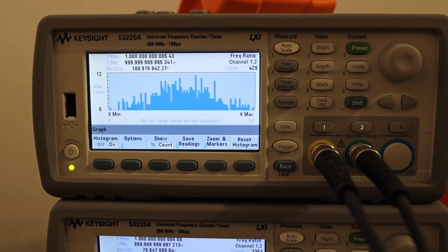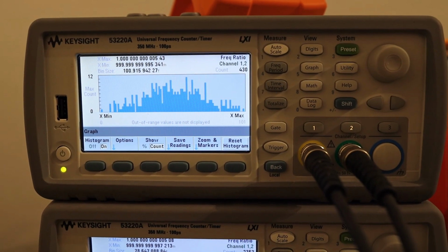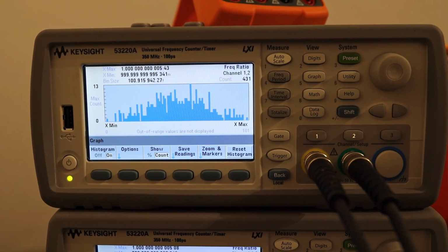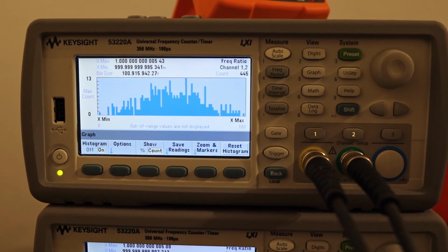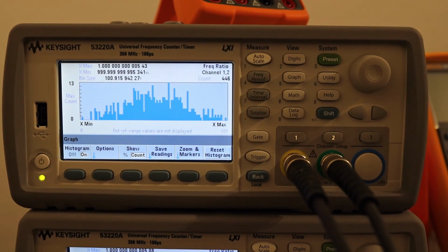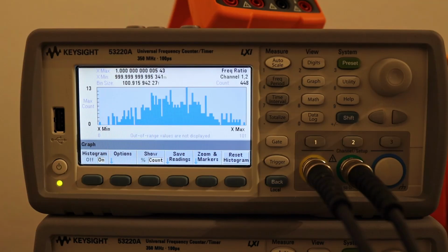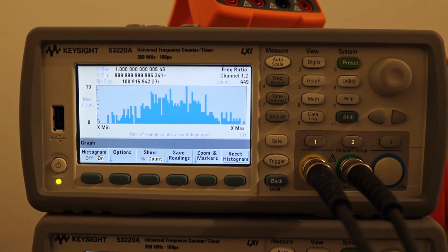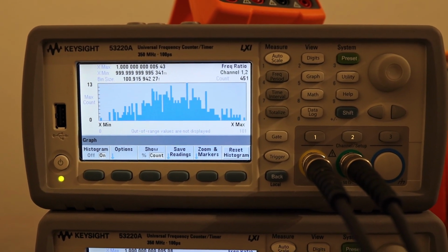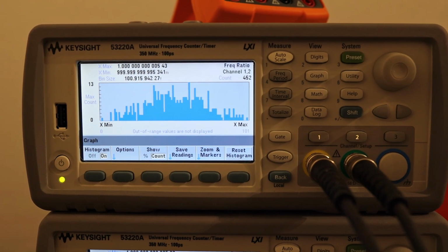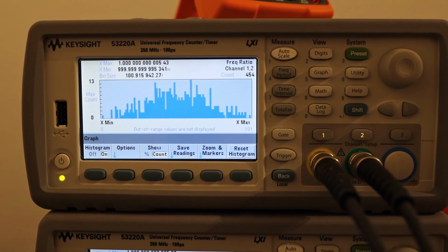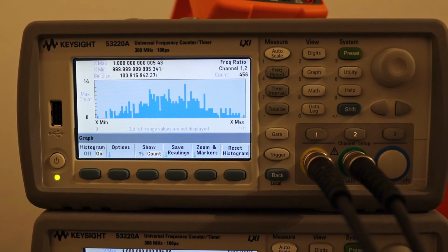you know, one driver drives 2 channels, channel number 1 and 2 driven by the same driver, 3 and 4 driven by the same driver, and 5 and 6 are driven by a different driver. So driver to driver difference is around 100 femto for 102 bins, which results to around 100 microhertz deviation from clock to clock for 10 megahertz.